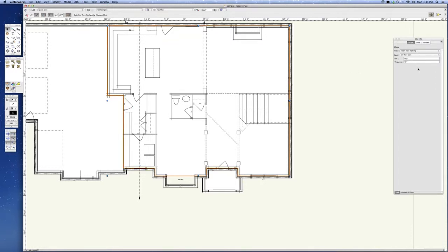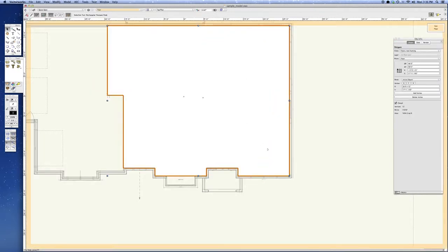Then go to the floors menu, and if you see over here, I've already made it a floor. My bottom Z is -10 and my thickness is 10 inches. That just accounts for a 2x10, 9¼ inch floor joist with 3/4 inch plywood, so it accounts for that. Later on, right before we send the next phase to the client, we would have also wanted to get a calculation on this area, which is, I always round it up, so 1,635 square feet.